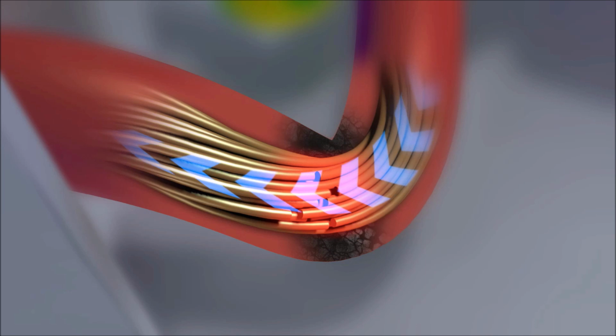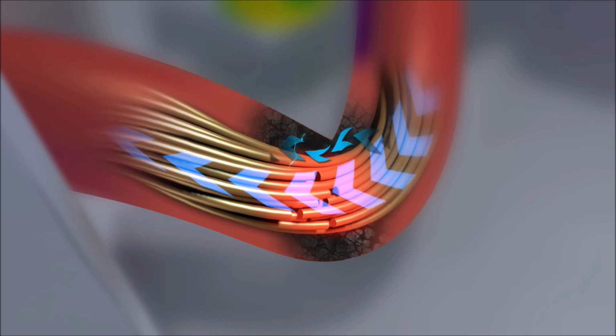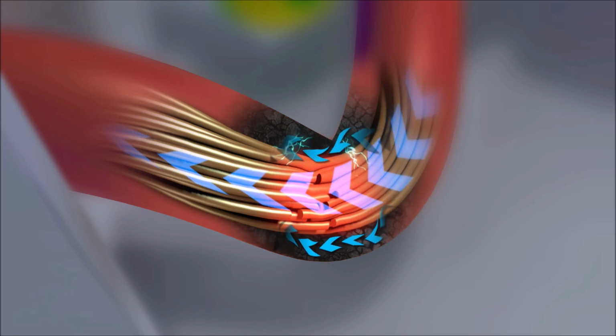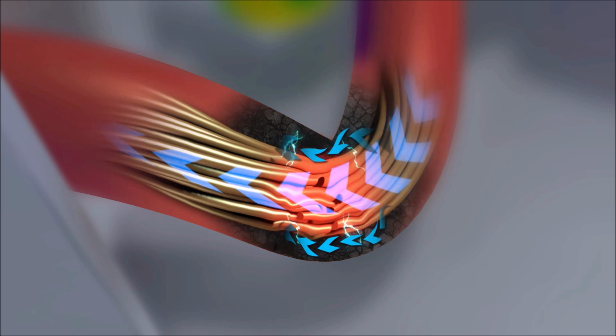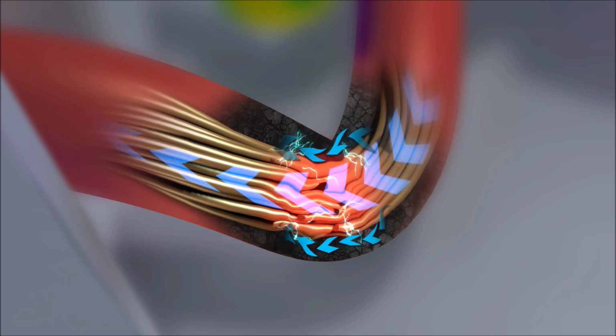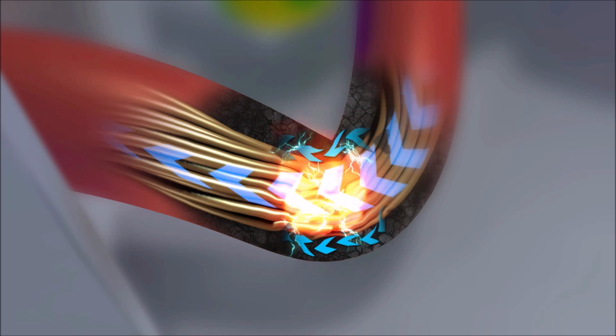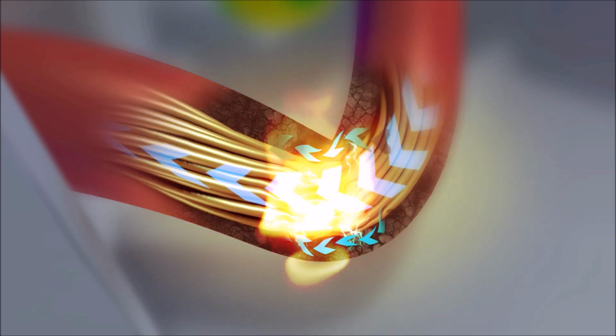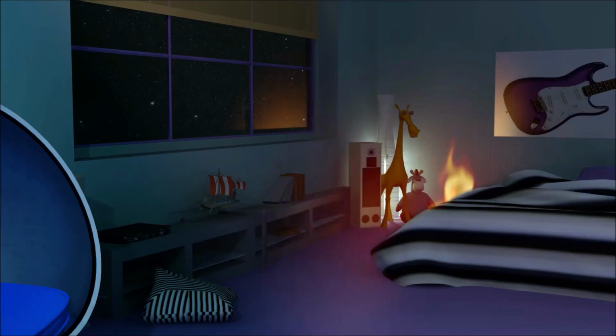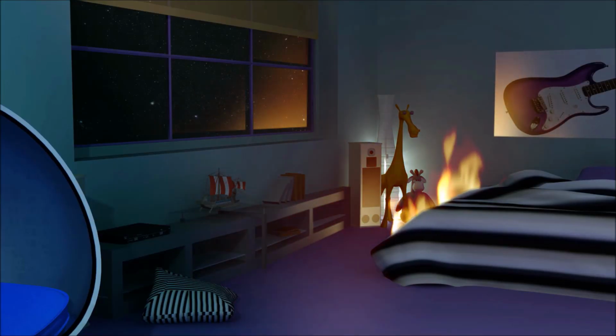The burned area acts as a conducting material. To flow through the burned material, the electric current produces arcs. These arcs burn even more insulation, which allows for more current to flow, accentuating the hotspot and producing more arcs. When there is enough burned material, the wire catches on fire. This is how a highly localized problem with a single wire can turn into an unforeseeable tragedy.